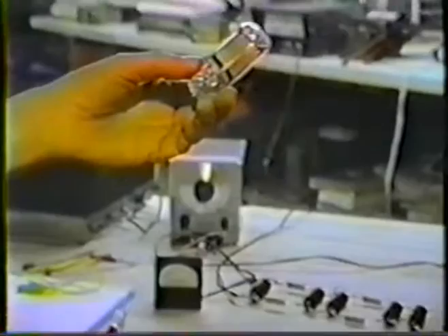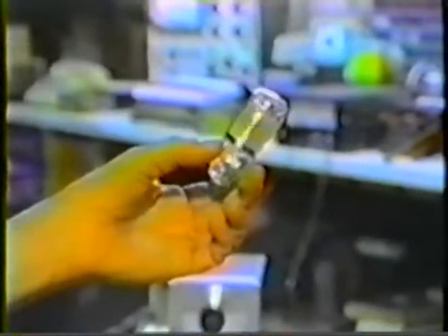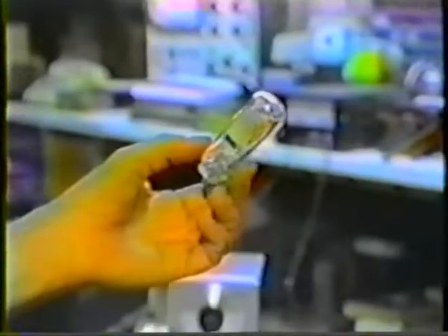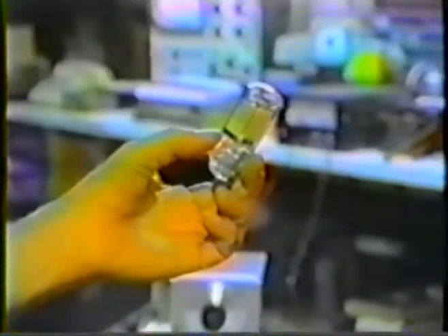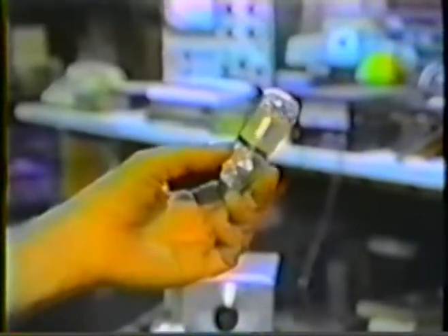We can focus at that range. There we go, we got it. You can see there's two, let's get a little better focus there. There we go. You can see there's two photo plates, which are semi-facing each other, which is different than your normal photo tube construction because usually you only have one plate. In this case, the anode wires are in the back, and those are photoemissive surfaces too.